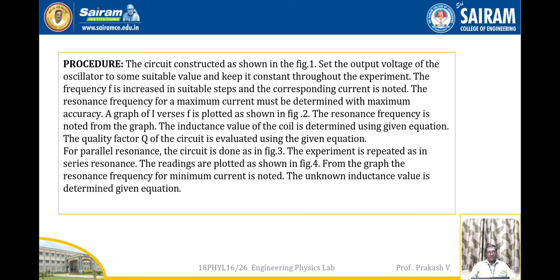For parallel resonance, the circuit is also as shown in the figure. The experiment is repeated as in series resonance. The readings are plotted as shown in the figure. From the graph, the resonance frequency for minimum current is noted down. The unknown inductance value is determined using the given equation.